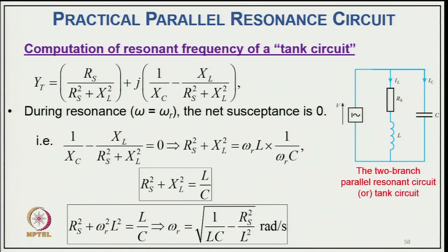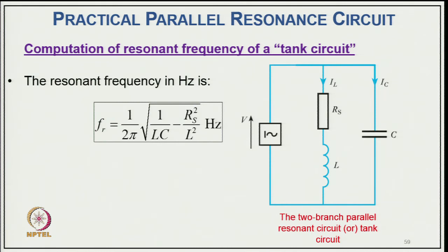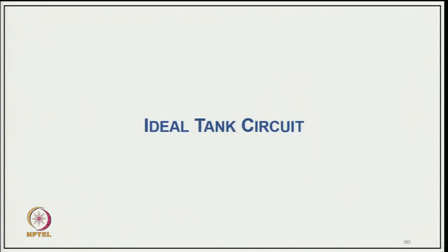So, that is the resonance frequency of your tank circuit, of course, with the practical tank circuit. The resonant frequency in hertz is f_r equal to 1 upon 2 pi under root 1 upon LC minus R_s square upon L square hertz.